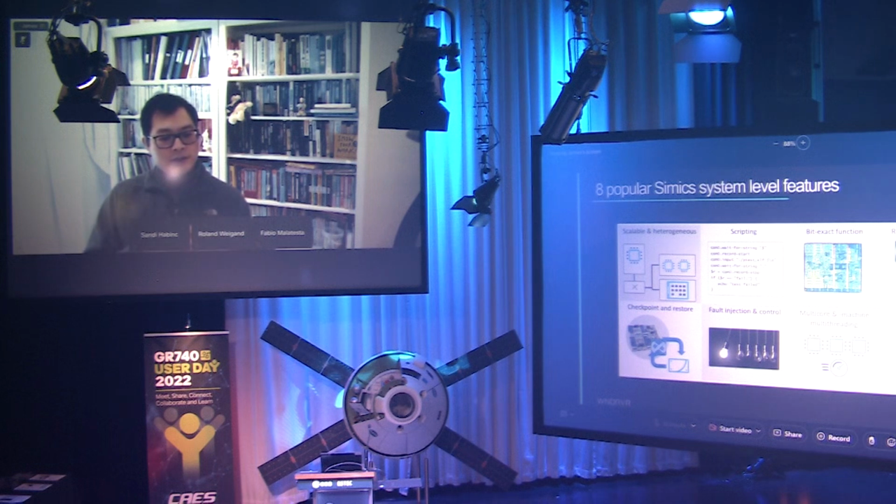In a simulator, which differentiates it from an emulator, there is the ability to control and inject different fault conditions inside a simulation. You can create a single event upset very easily in a simulator, and you can corrupt the memory and test how your software is going to react to it. And Simics is built modular and extendable, so it's a platform that allows you to extend the functionality and create the tests and modules that you need to run the tests that you care about.